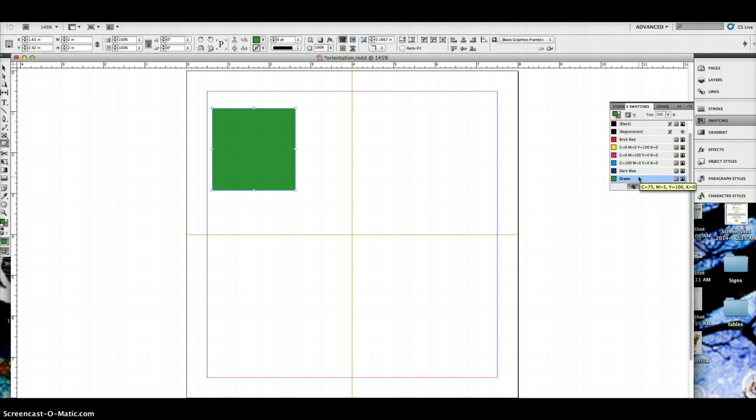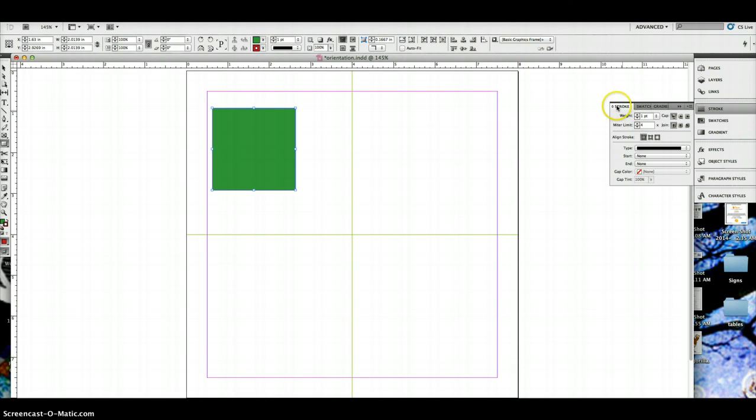Now click the stroke button. So select the stroke, and you'll see that it now comes to the front. Click brick red on the swatches panel. You'll notice it says brick red, and it applies it. Now notice it's a little bit hard to see, so what we're going to do is open the stroke panel. It's the tab over in the swatches panel, and where it says weight, go ahead and highlight 1, press 6, and press enter, and now you can see that the red stroke is visible.